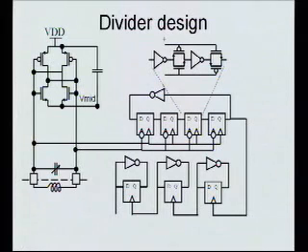Does that make sense? So basically, this power savings is coming because I can drive my switches differentially straight off my inductor, and so get a big reduction in input drive power, and then only consume power in my inverters. And I did an analysis on the trade-off between how many stages I have in here, and how many stages I then needed in my successive divisions. And 8 turned out to be about the right point where you get the least overall power consumption.